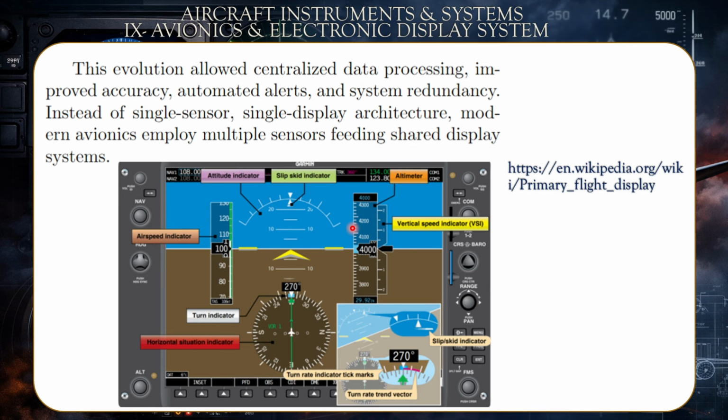For example, here in this image down below, you have the attitude indicator, okay, at the same time the skid or slip indicator, which is this one. So when the lower white arrow is moving away from the upper arrow, you would understand that there's a slip phenomenon going on, whether to the right or to the left. To the right here you have the altimeter, or measurement of height, and the VSI next to it, which is the vertical speed indicator. It would be 0 in leveled flight.